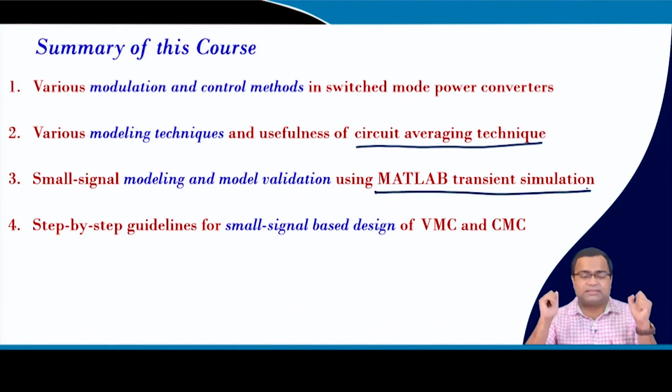Then we also discussed step by step design, and this MATLAB transient simulation I have demonstrated in multiple lectures step by step. That means I have demonstrated the MATLAB code, and I have also demonstrated how to plug in those transfer functions, obtain the step response, and then how to add the offset point and compare with the actual switch simulation. So, this is a very useful technique. And also I have given a lot of resources for MATLAB.